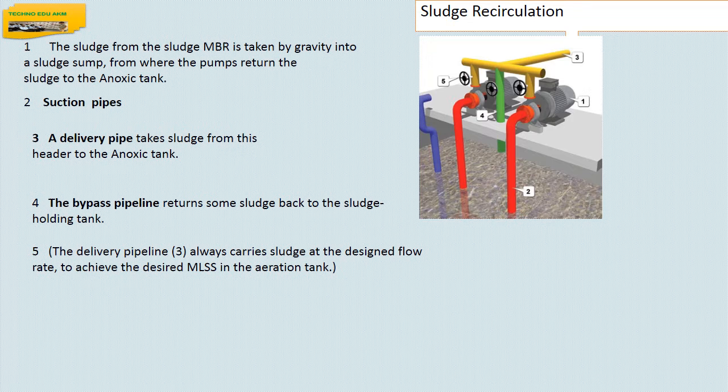The sludge handling mechanism is the centrifuge. Thickened sludge from the aerobic digester is pumped to the centrifuge to dewater the sludge and form a cake. The cake will be removed manually and disposed of as manure or carried out. Filtrate will be diverted to the aeration tank.